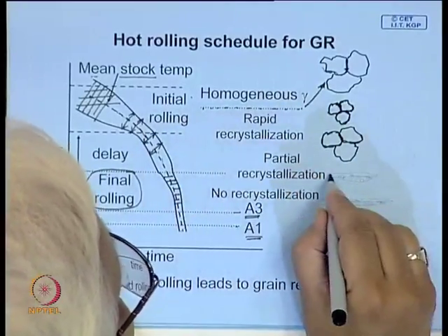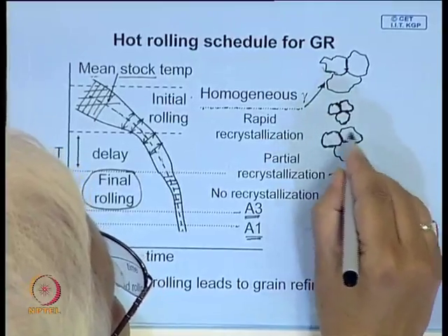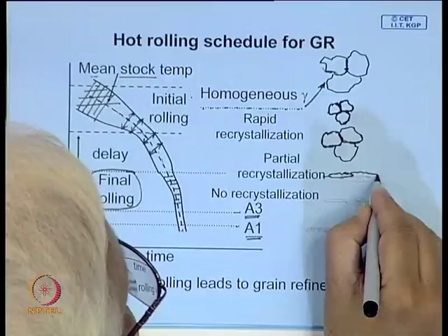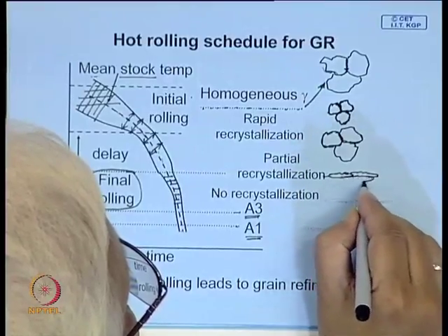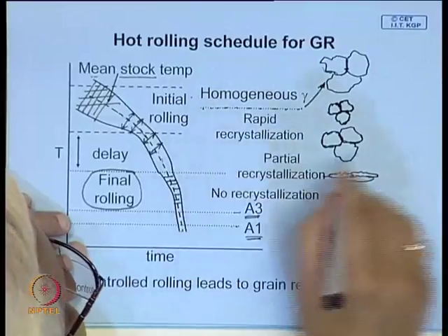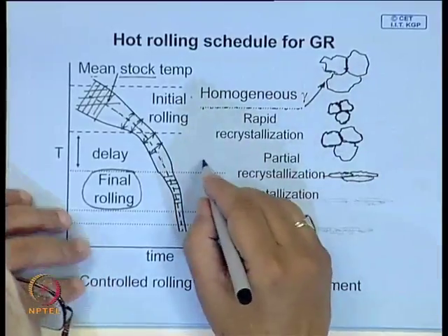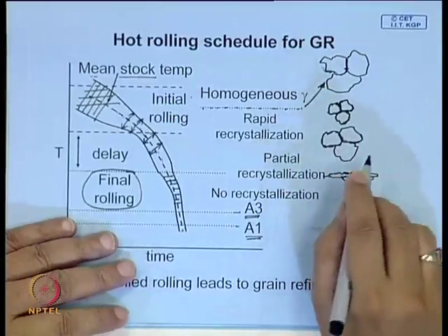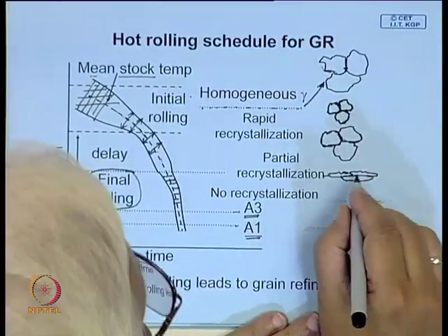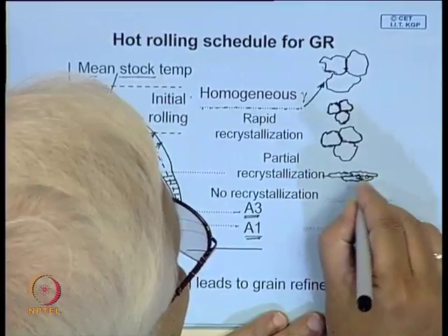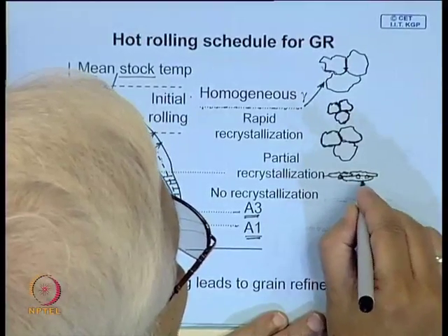So, there is a stage here where these austenite grains of this size get elongated like this. Since you are giving a very large reduction, the temperature also is substantially lower. So, we know that the recrystallization rate also will be low. So, here if at all recrystallization is taking place, there will be very few recrystallized austenite grains.